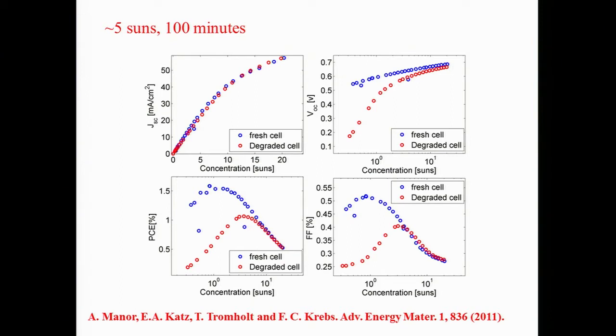We measured PV performance not with a solar simulator, but with sunlight. I will talk about it in more detail at our COST meeting. In Sde Boker at noontime, plus or minus 2-3 hours, we have an air mass 1.5 global spectrum. We also have a huge ratio between direct and diffuse light, so we can concentrate sunlight, because physics forbids concentrating diffuse light.